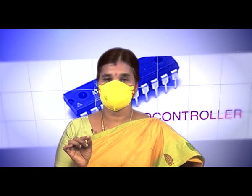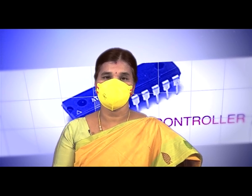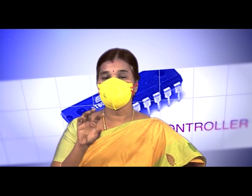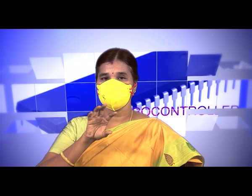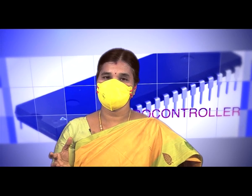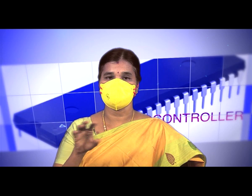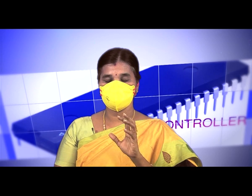The control signals are read bar and write bar. Read bar represents the read operation. When the signal is low, the read operation will be performed, otherwise there is no read operation. When the read operation is active, it will read the data from the memory. The other one is WR bar, for when you want to write the data into the memory. When the WR bar signal is low, the controller can write the data into the memory. So read bar and write bar define the direction of the data lines, either inwards or outwards. This is the general requirement for memory.